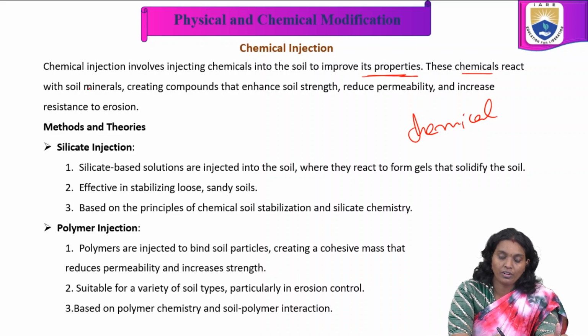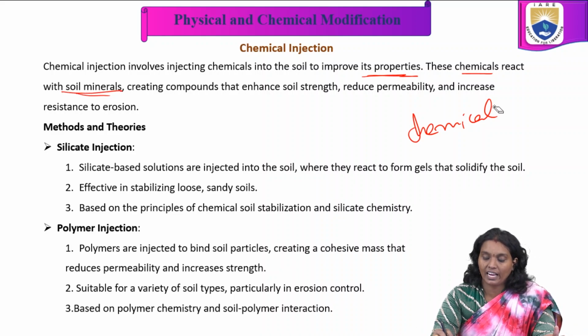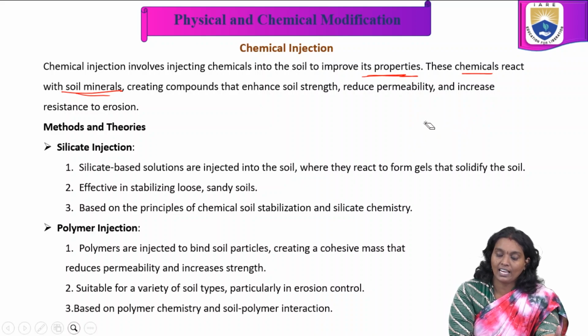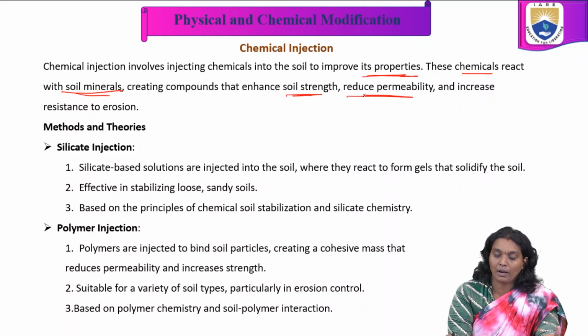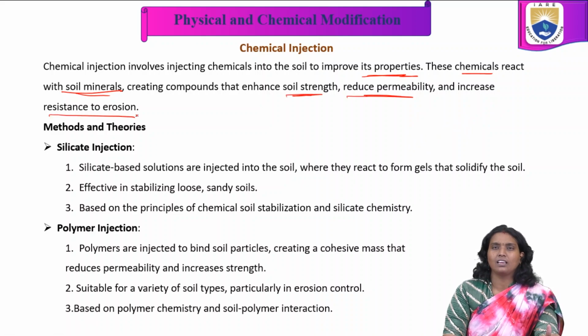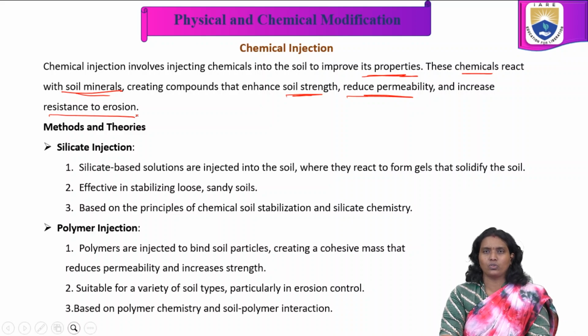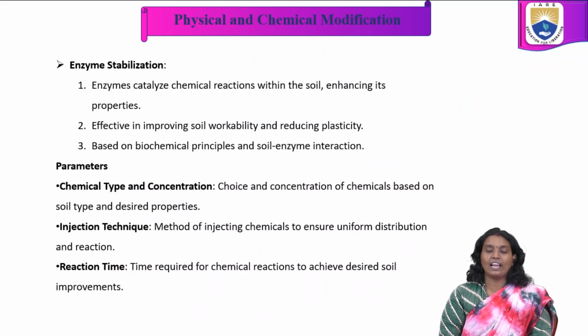They are going to interact with soil minerals, creating compounds to enhance the soil strength, reduce permeability and increase the resistance to erosion. In this, coming to the methods: silicate injection, polymer injection and enzyme stabilization.